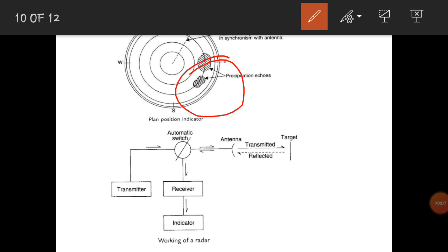The backscattered radar power from precipitation particles is proportional to the summation of the sixth power of particle diameter. Drop size distribution has been measured in many types of rain. Usually the coefficient increases and the exponent decreases with increasing convective intensity, even for similar type storms in the same geographical area.